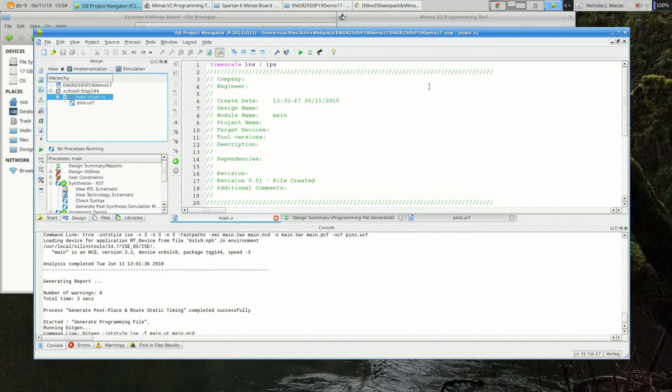So that's basically the whole tool chain, right? Now if you're working with a board like this, it's a different chip. It's a Spartan 3, and it has a different package. So different family, different part number and package, but you put those in the beginning, and different pin numbers, right? If I want to connect to these switches here, they're going to be different pin numbers, but I find the documentation for this, and I put those in my configuration file. The rest of the process is identical.